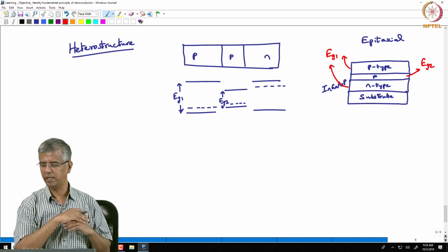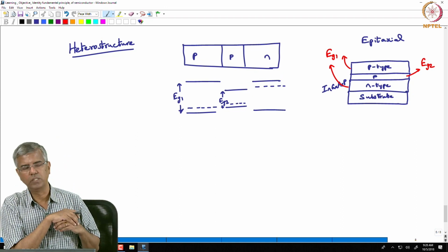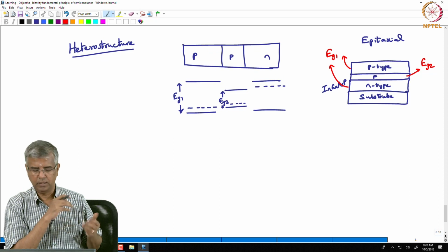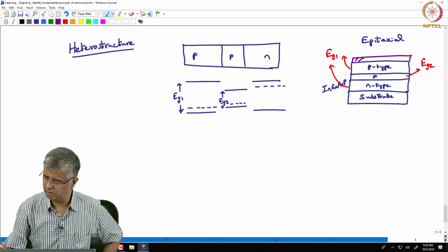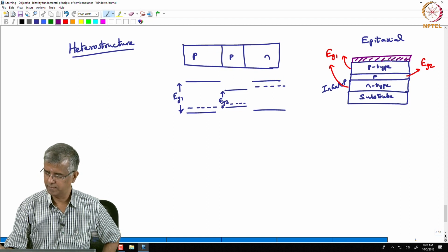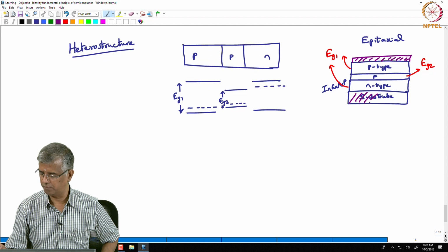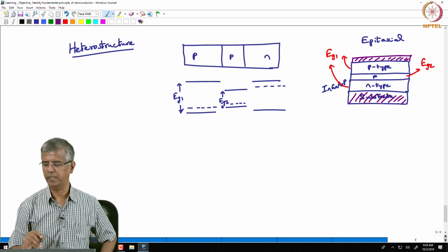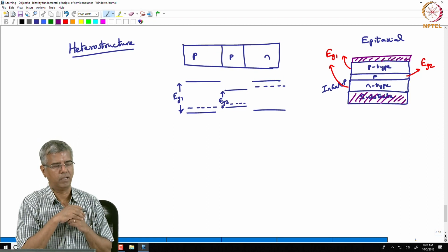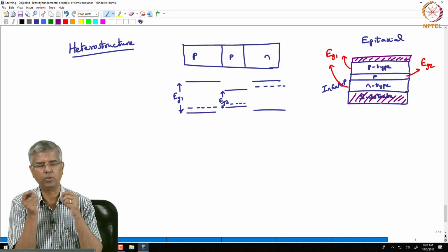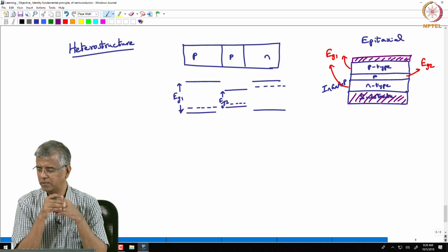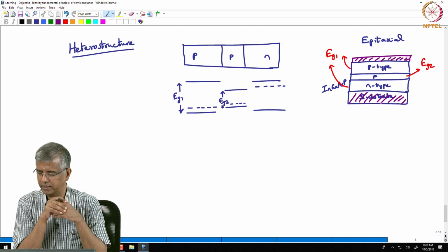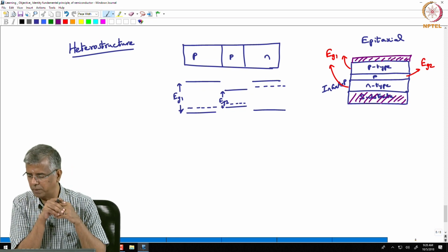Okay. So, but your overall structure is going to be like this. This is just basically all these layers are sandwiched between two metallic contacts. So you deposit a contact over here, and this substrate itself, you may have a contact over here, and then you have a possibility of connecting that to an external bias source, and you have your light emitting structure or your detector also, depending on what sort of bias you put.